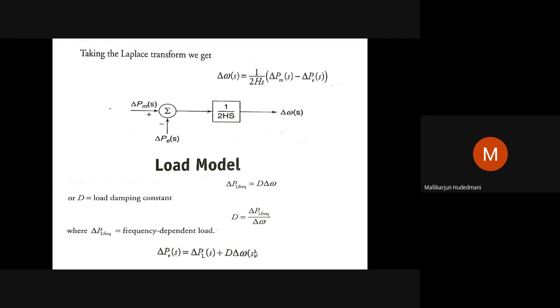How is that change in frequency? If there are sensitive loads, how is that change in frequency? This is experienced by the governors, because governors are the ones going to correct for the change in frequency. So they will experience the requirement of change in their set point. That we will see when we go to the numerical problems.